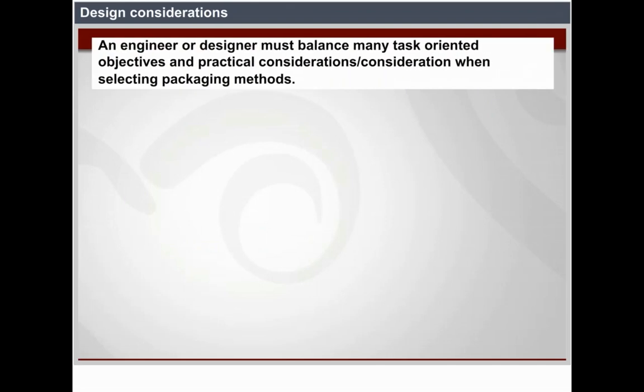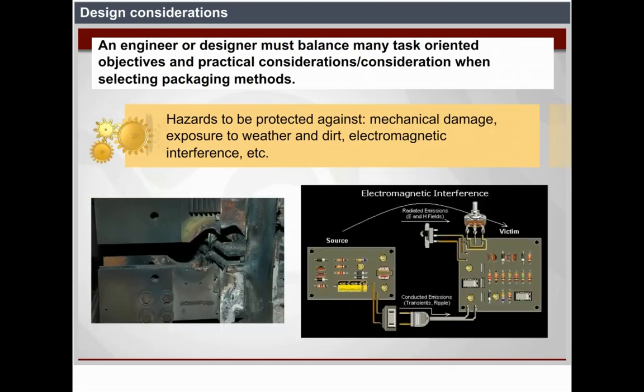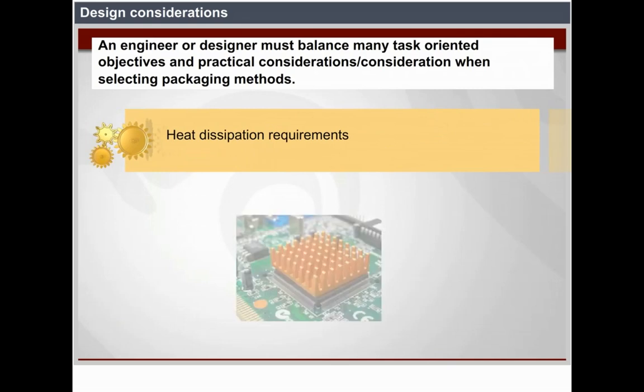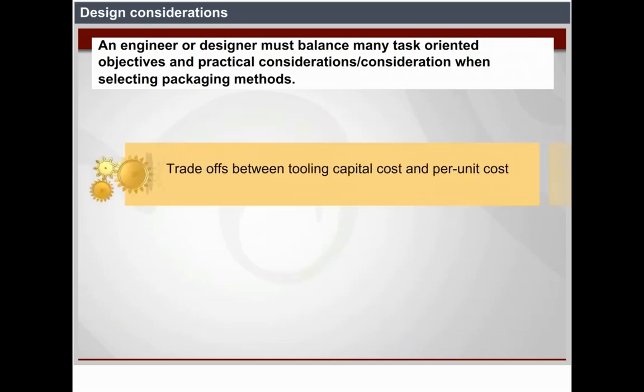Design considerations. An engineer or designer must balance many objectives and practical considerations when selecting a packaging method. Hazards to be protected against: mechanical damage, exposure to weather and dirt, electromagnetic interference, etc. Heat dissipation requirements, trade-offs between tooling capital cost and per unit cost,